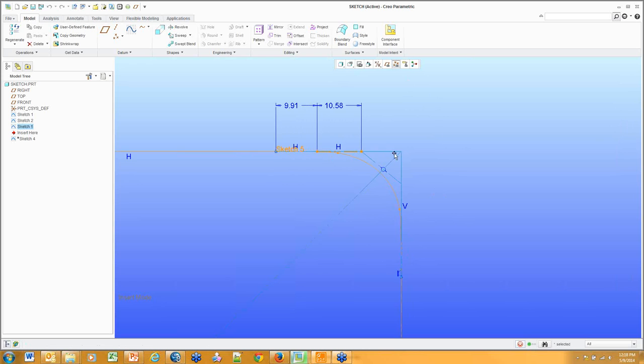We saw this earlier. However, should I want to change the curvature of the actual spline, query the datum point, double-click on it to go into edit mode, and now we can specifically hone the curvature of the spline.